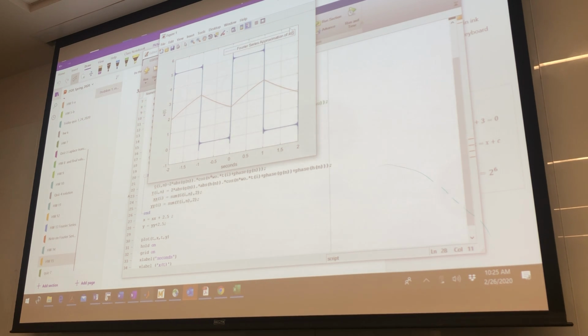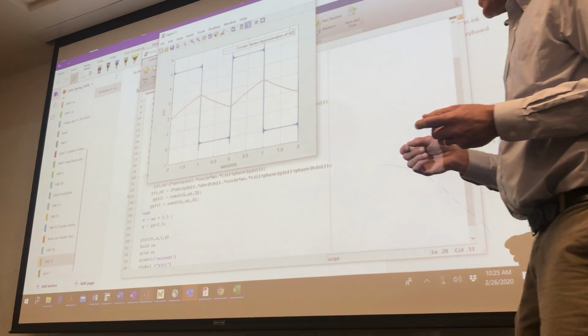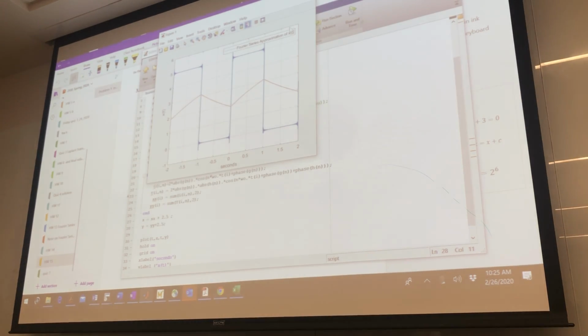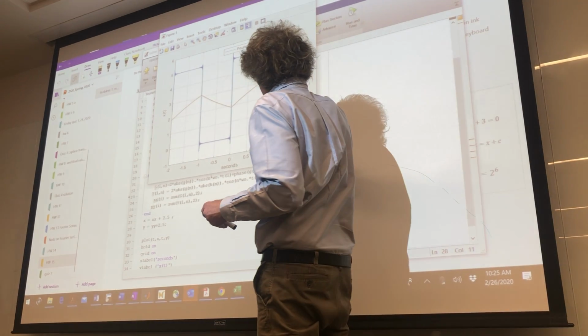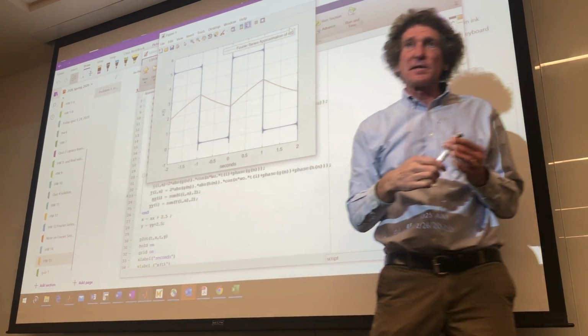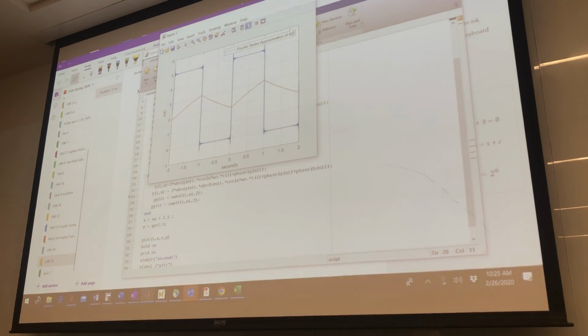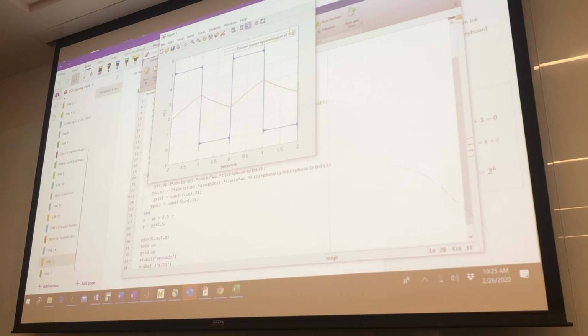All right. Now that's the actual output waveform, and I've got to talk about this for a second, because this is interesting. When I have an inductor here, what an inductor does, it has a very large impedance, think of it this way, for anything that tries to change fast. So when the waveform goes from here to here, the impedance is huge. It's basically not even in the circuit. Do you follow me on this, class? An inductor resists changing current.